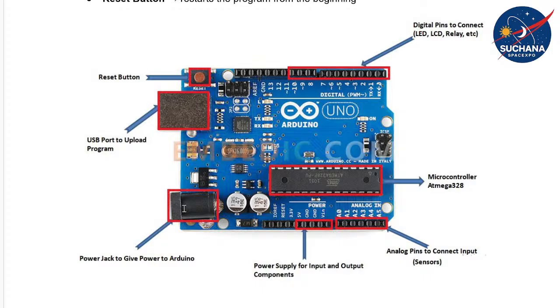Now I will tell you one thing. If you directly connect an LED to a battery, say a 5-volt power supply, the LED would immediately start glowing. Now instead of a battery you connected it to the Arduino UNO. One pin should be connected to ground, which is always common, just like connecting one terminal to the negative of a battery.